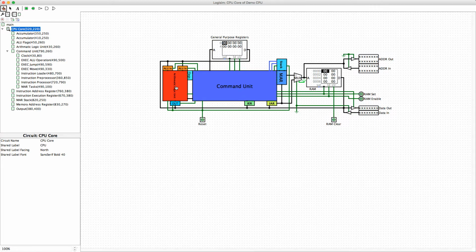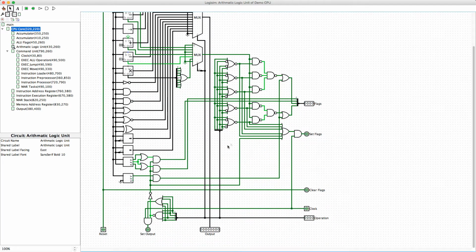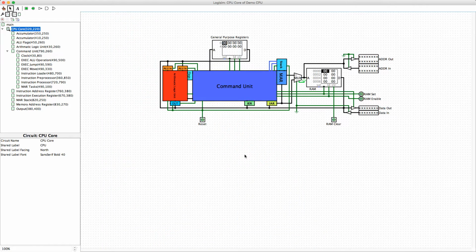And let me show you the arithmetic logic unit. I have 15 operations that can be performed by this arithmetic logic unit, and divide is not one of them. I can add, subtract, negate, increment, decrement, multiply, do all 7 of the logical operations, do shift operations, and compare. But I cannot divide. At least there's no hardware implemented divide. This is what's left over from my attempt to build an 8-bit CPU without watching Ben Eater's videos.